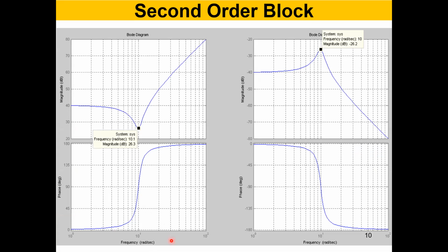So this is what you get. On the left hand side, this is the magnitude and phase plot for a pair of zeros. On the right, this is the magnitude and phase for a pair of poles, right? You saw this 40, remember the 40 dB thing. Earlier, for a first order case, you saw 20 dB. Now this time 40 dB because two poles. The single pole like 20 dB, two poles like 40 dB. So remember these relationships, right?